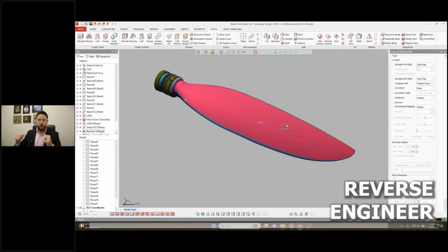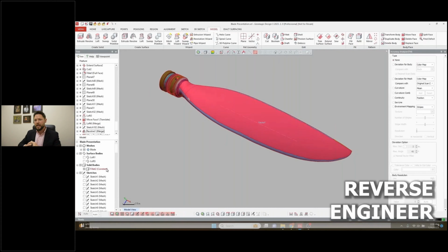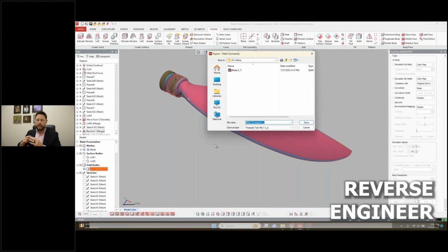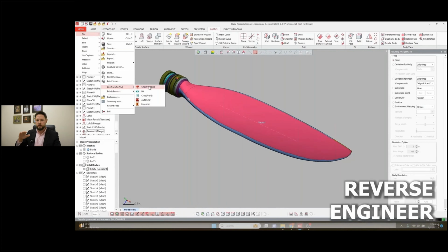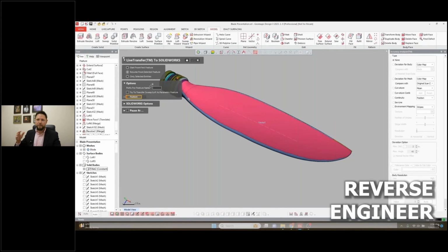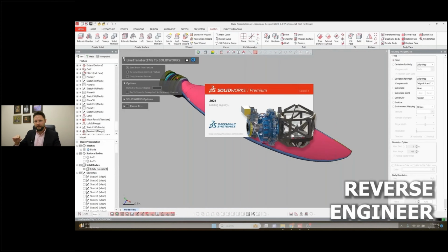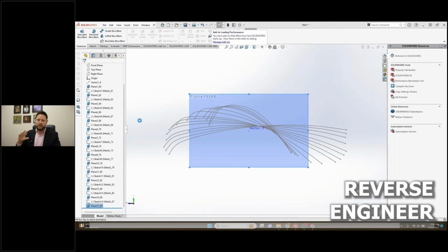Last step, double check your accuracy analyzer, make sure you're accurate everywhere on your mesh. And then from there, we can export that CAD file as just a basic solid with no history tree. Or what's really exciting is we can go to our favorite CAD package and transfer our tree line by line over to it and have our parametric features there.